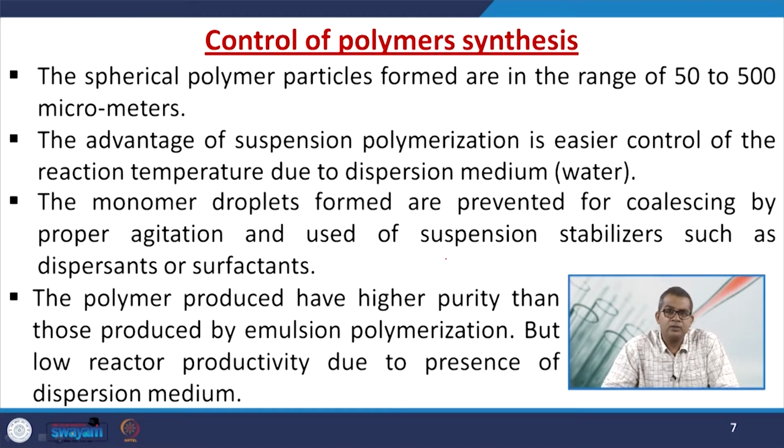to control with respect to the reaction temperature due to the dispersion medium, that is water. So, water is universal, you can say, and the particle size controllers usually dissolve in water. The monomer droplets formed are prevented from coalescing by proper agitation and the use of suspension stabilizers such as a dispersant or surfactant.